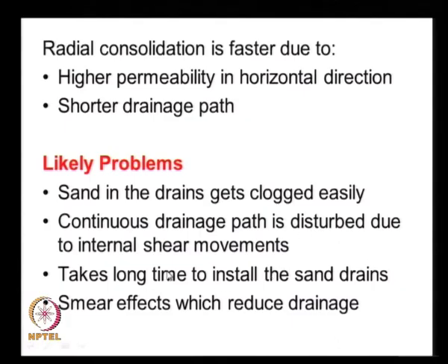Because of the complicated installation process, there are many cases where the flow path is disturbed because of the smearing of the clay soil all around. It is basically remolding of the clay around that reduces the drainage capacity of the sand drains.